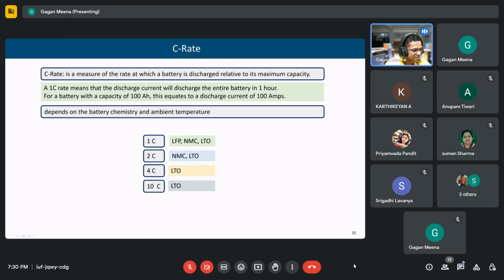But if we put an onboard AC charger of a very high capacity, high rating, then the weight of the vehicle will increase, the cost will also increase, and the space required will also increase. Everything will increase. That is why we are not having these big chargers onboard the vehicle. We are having off-board DC chargers, very fast chargers.